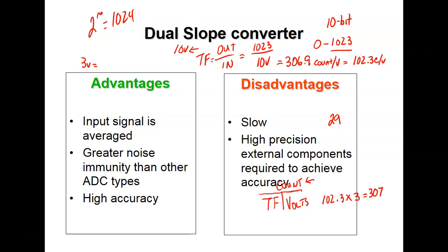Well, if we did the volts per bit, we'd switch that thing around. But you should come up with basically the same answer, right? Then you have to convert it over. So it's best to just say, what are we getting out? We're getting counts out. What are we putting in? We're putting volts in, right? You understand? Then we came up with that, and now we know this is going to be 307.